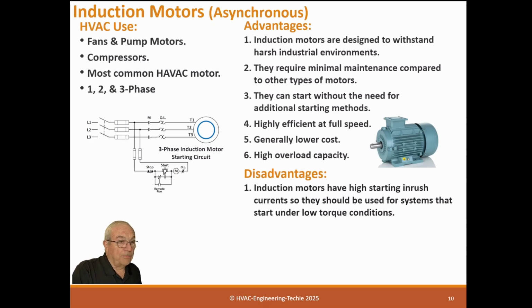A fan starts up, there's no air moving for it, so its load is 0. And as you turn faster and faster, you get more and more load, the torque goes up, and that's perfect for an induction motor. A conveyor belt for an induction motor is not a too good idea.